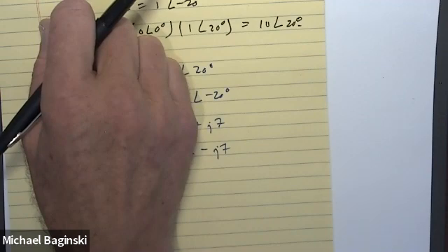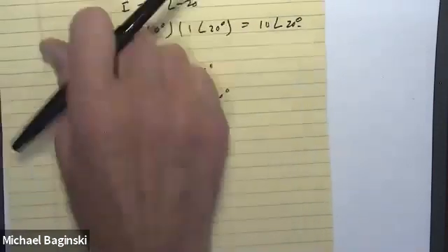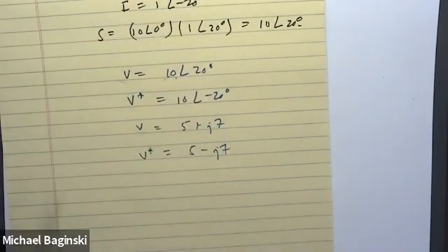But if you understand the concept, when you see something that has a current leading a voltage, you would know that that, in fact, is an odd thing. And then you wouldn't put a capacitor in parallel. You would put an inductor in parallel. In other words, if the system is primarily reactive caused by an inductor, then the element you're going to put in parallel is a capacitor. If it's got a capacitive nature, with current leading voltage, then you're going to put an inductor. And that sort of makes sense. Whatever the system's got the most of, inductive reactance, you want to put in parallel something that's got capacitive to get rid of it. That kind of is intuitive, isn't it, class?